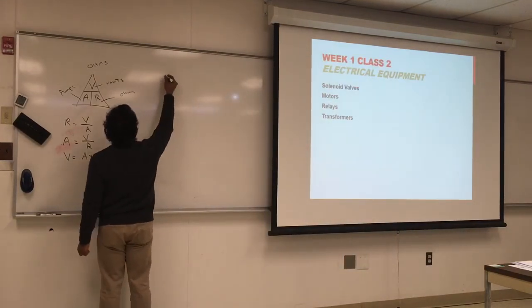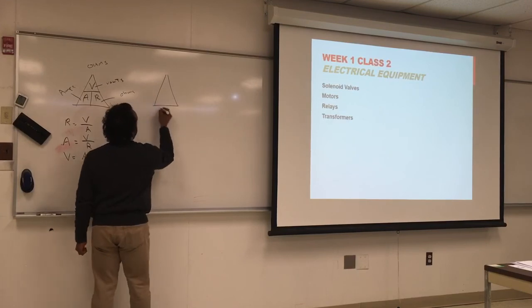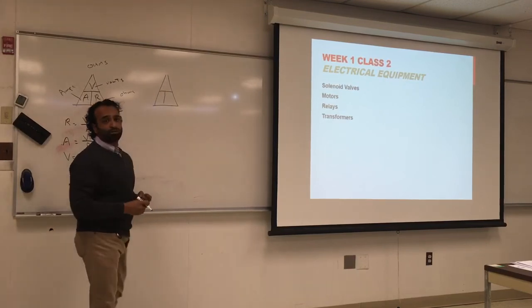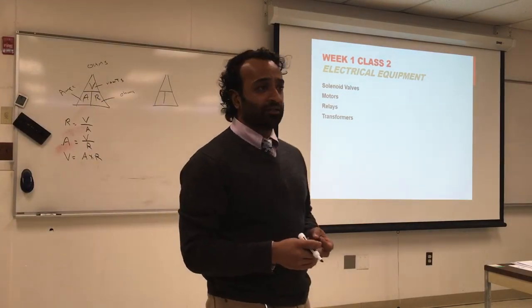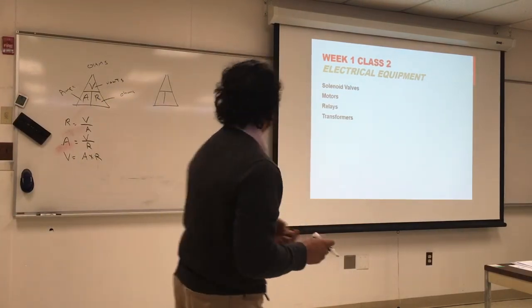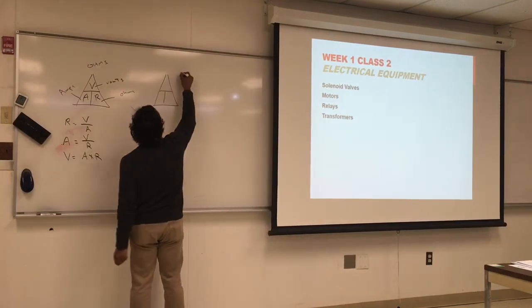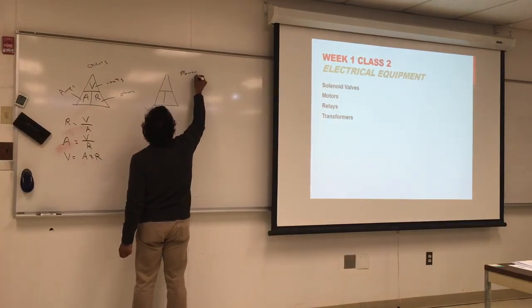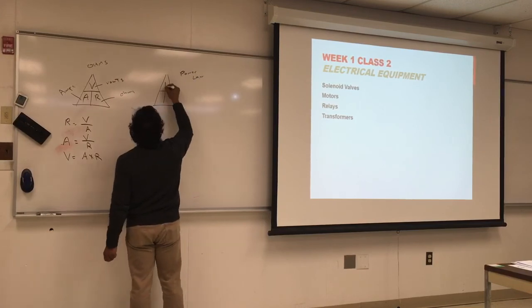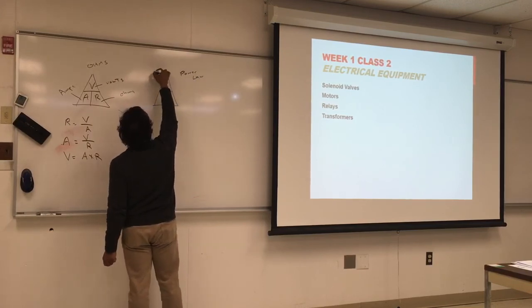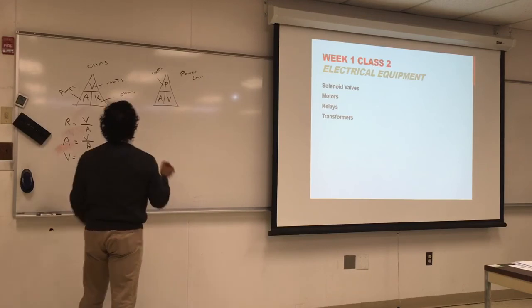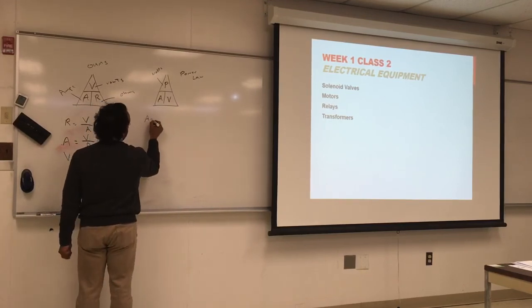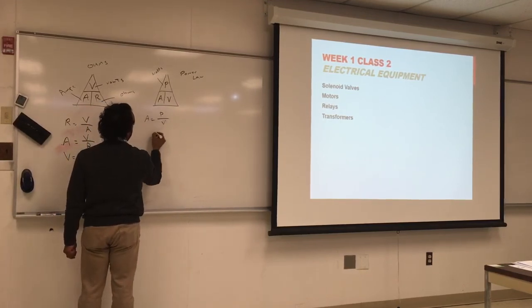Second thing is power law. That's important also to calculate cost, to calculate how much power you're going to be withdrawing, and see if the circuit can handle the amperage draw or not. So that's the power law here. Power is in what unit? Watts. Voltage and amperage, same thing goes. Amperage is power over voltage.